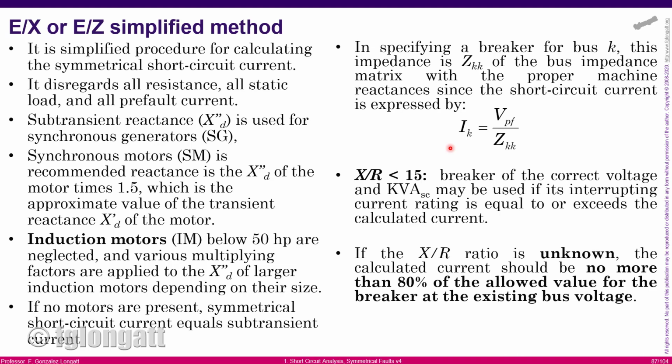Well, many years ago, ANSI started to create the standards C37 and C57. They are used for simplified short circuit calculations in the US. Here in Europe, we also have the standard IEC 60909, which covers simplified short circuit calculations.